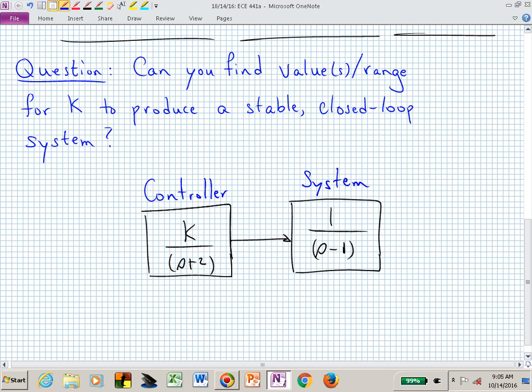It has a positive pole, doesn't it? And in that case, positive poles are not really positive in the sense of right or positive. It's actually an unstable system if the pole was in the right half plane. So this is actually an unstable system, and we want to stabilize that, which it won't be stabilized if we just had this cascade combination. We actually need to measure the output of that system and feed it back.